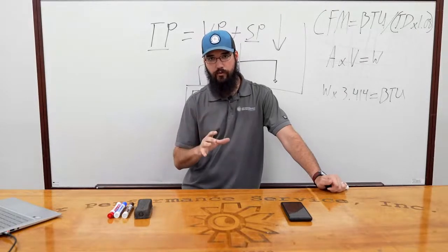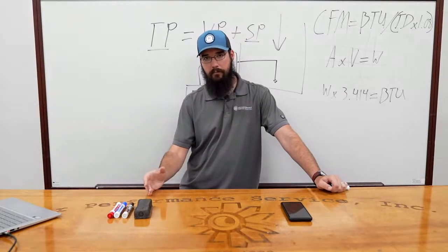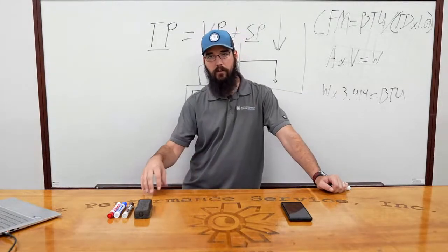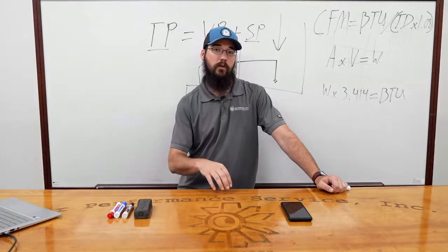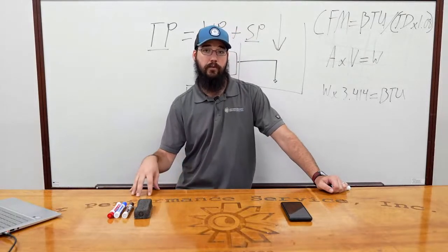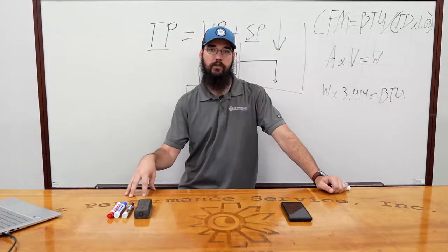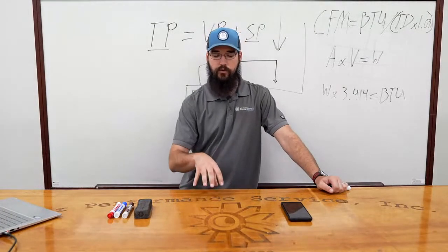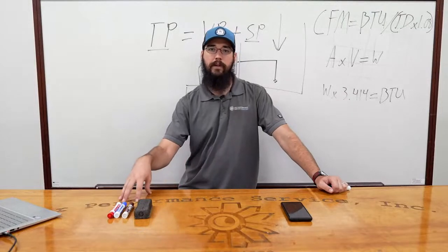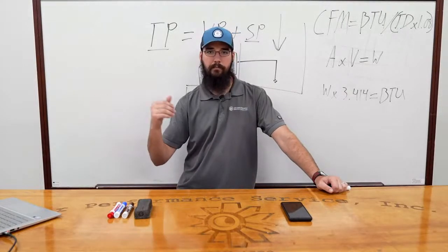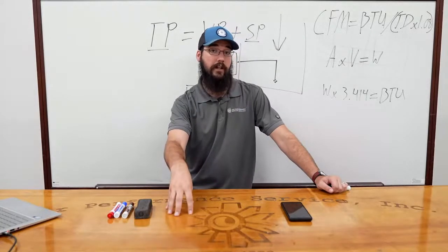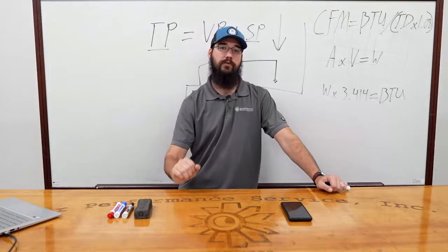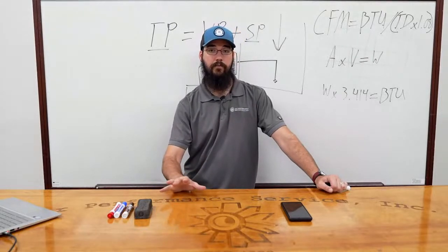What you should do is take everything I've said, maybe watch this a couple of times over, and take each piece of what I talked about along the way that you're not already familiar with, and then take that one piece and try to apply it. For example, the belt piece, or just understanding external static. Just start taking external static readings as part of your troubleshooting process. And do that one thing, just the one.